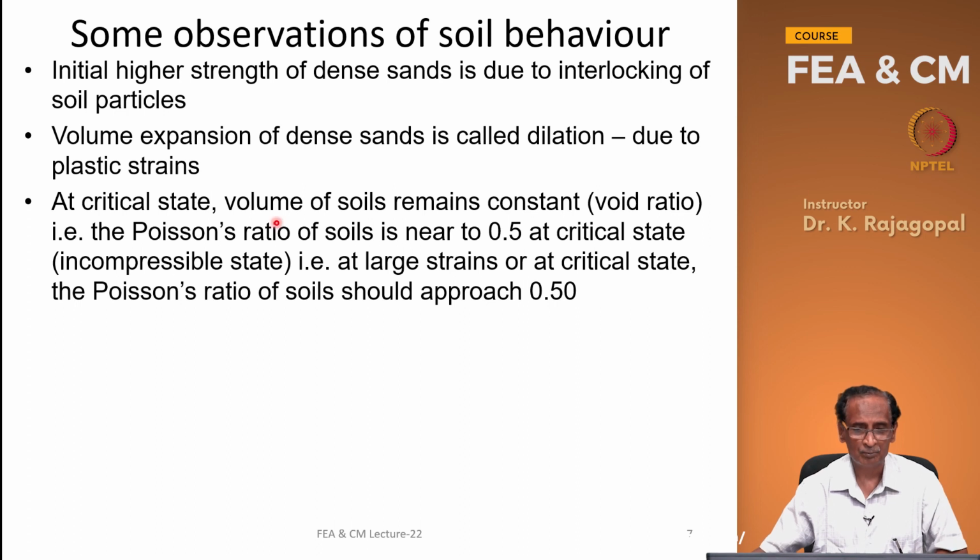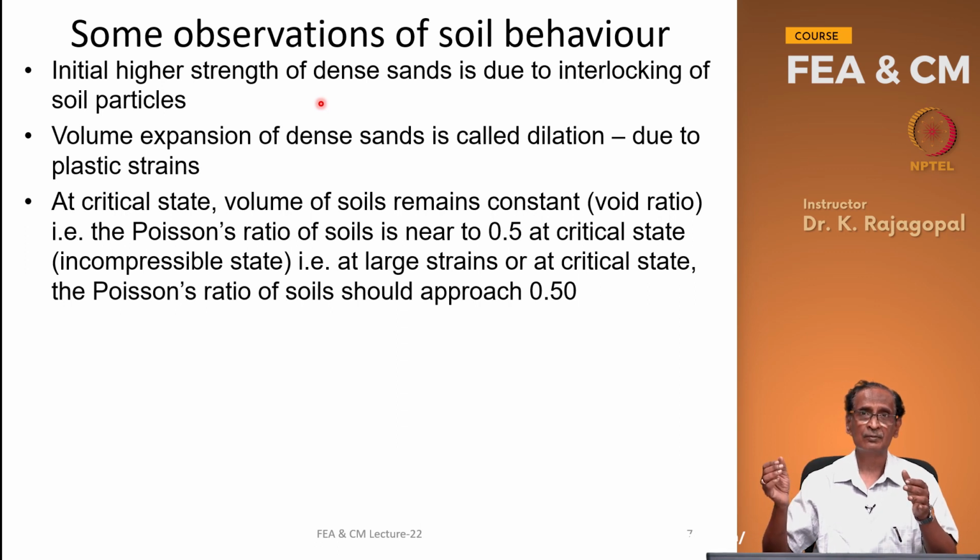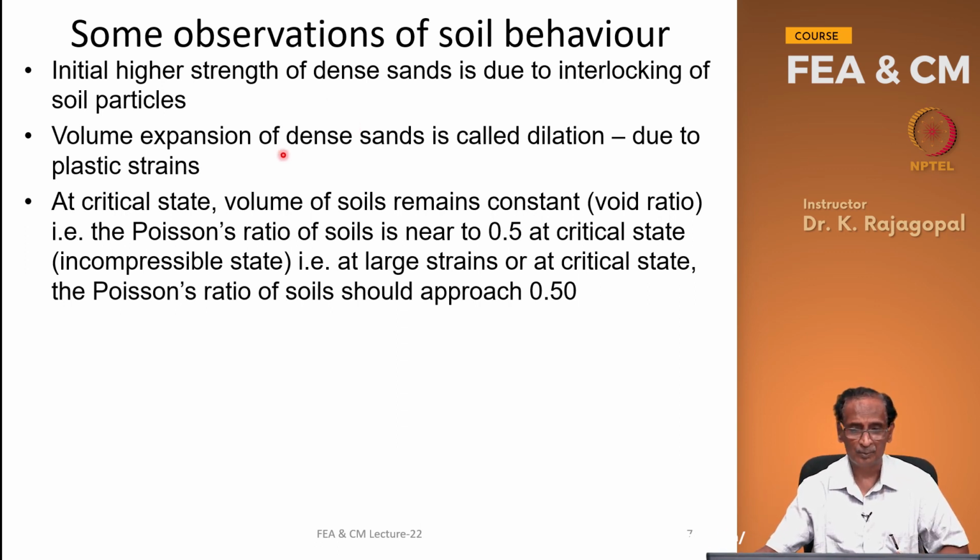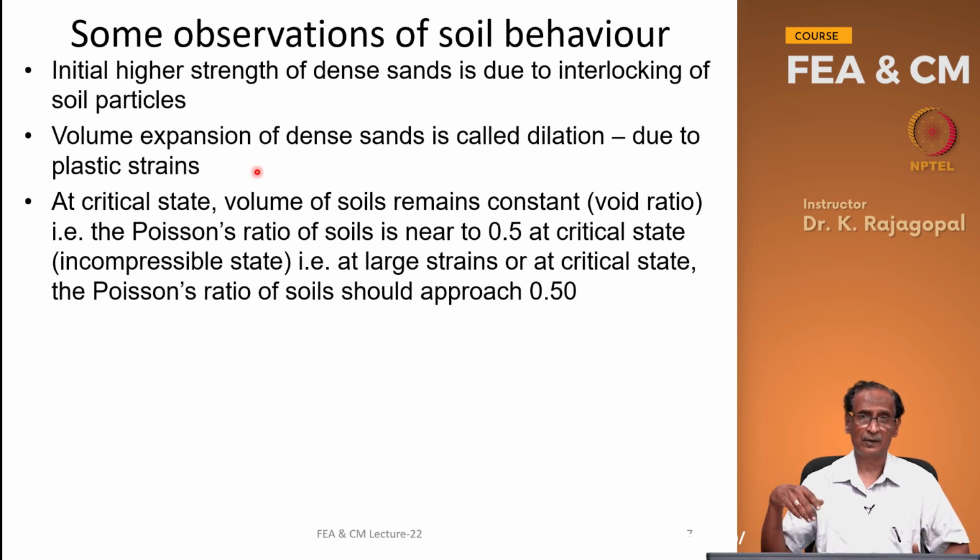And the initial higher strength of dense sands is due to interlocking of the soil particles, either because of the gradation or because of the particle shape. And the volume expansion is called dilation, and it's due to the plastic straining.